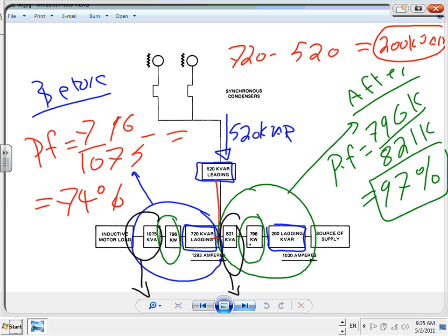This is one of the most important things to understand about power factor correction. Before you correct, the power factor is screwed up. After you correct, the power factor is okay. For example, if you corrected at the switch gear, then from the switch gear up to Xcel Energy, we're corrected. Below, from the switch gear down to the panel here, your power factor is screwed up.